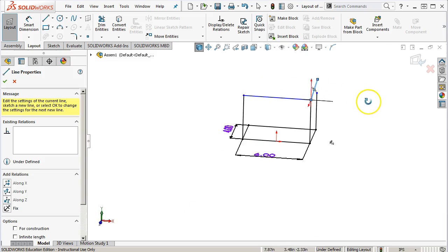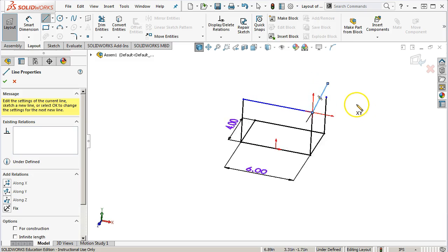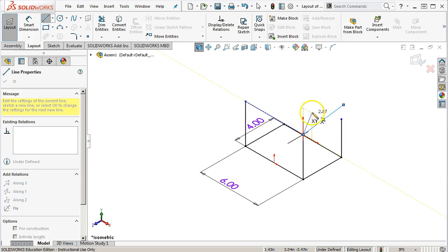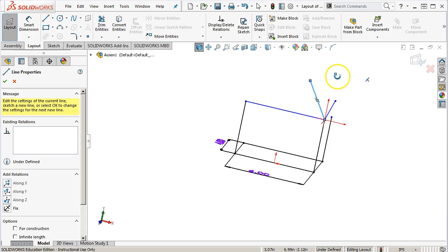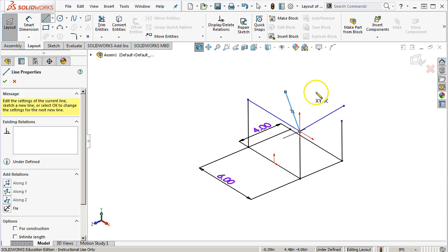All right, going in that direction versus I think I'm drawing back that way, but really those inference lines, that inference rectangle, those are giving me vector directions. All right, so looking at those dashed yellow lines, that's helping me with a visual reference to pick out which way I'm telling those things to go.